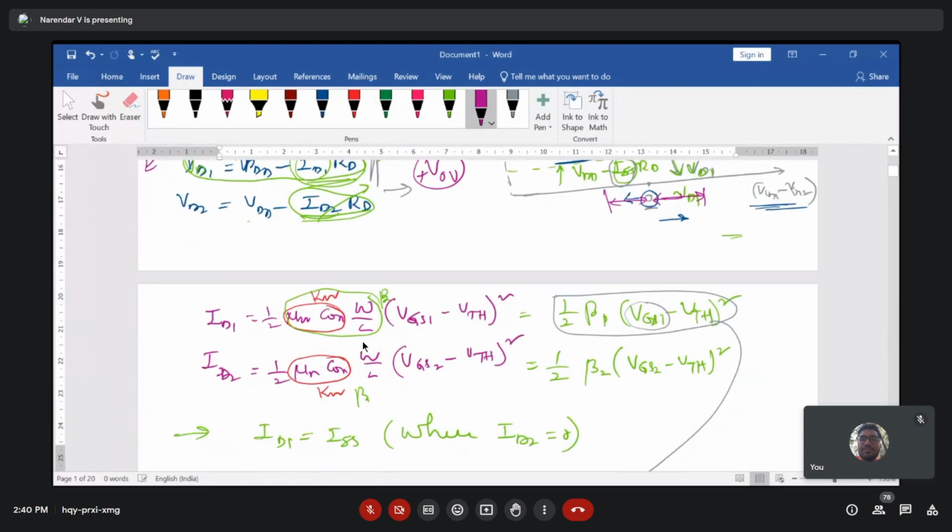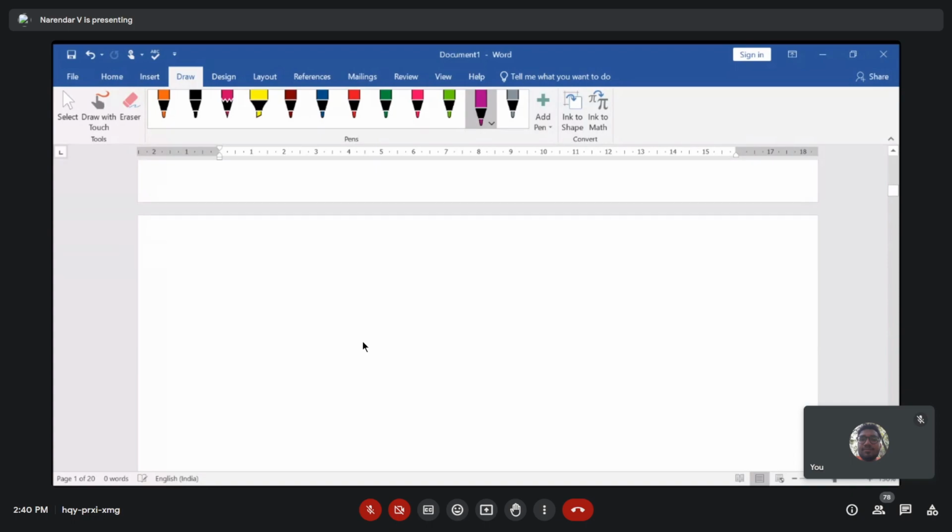this plot again, let me redraw it again here. What I'm drawing here is that x-axis is a differential input, which is V input 1 minus V input 2. It's a 0 point, and the maximum current here is ISS by 2 at this position, right?